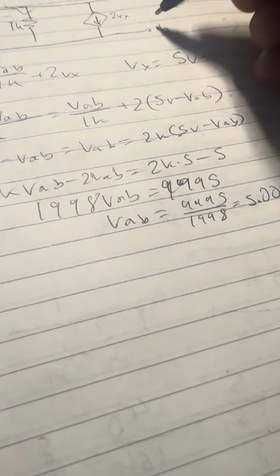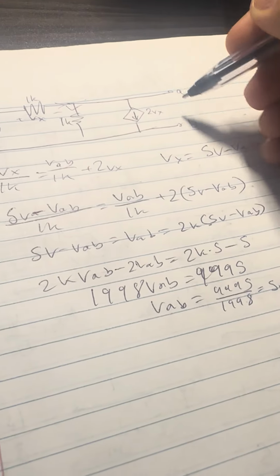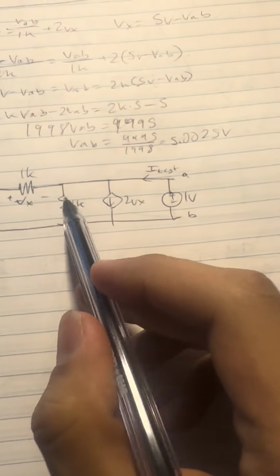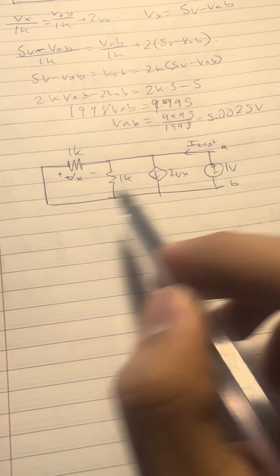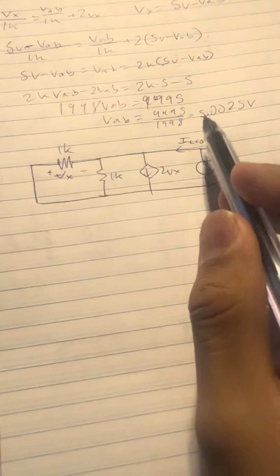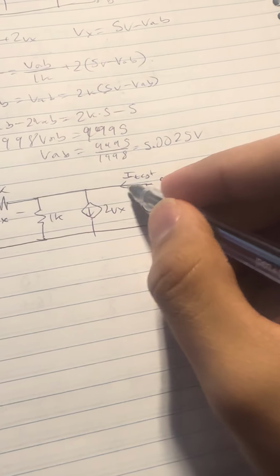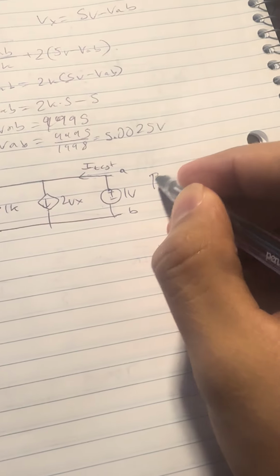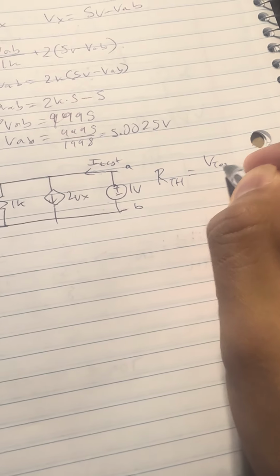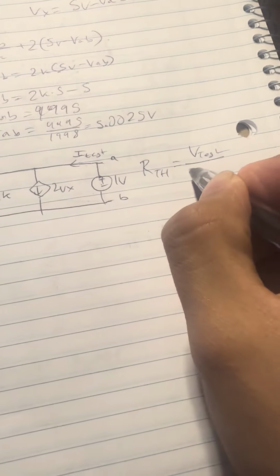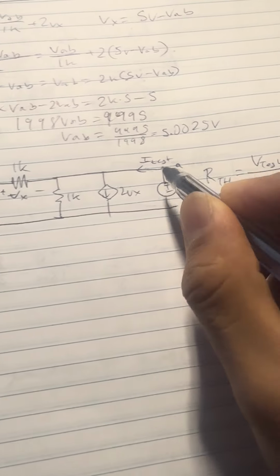I'm going to run the plus voltage source this way. So let me set up the circuit and I'll show you. Basically it looks like this, and we can use KCL to solve for ITest. We know what IV is, and we'll get ITest, and we can say that the RTH is equal to the V test, which is 1 volt, divided by the I test, which is what we're solving for. So let's use KCL to come up with the equation.